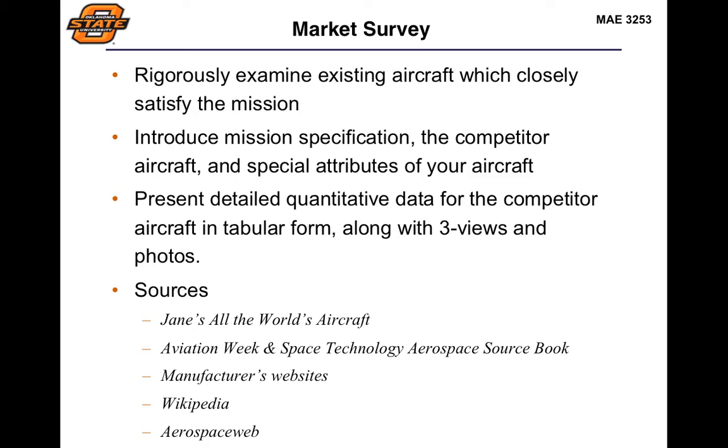Now, part of this benchmarking is looking at the market survey, right, where you go out and you look at existing aircraft which are going to closely satisfy the mission requirements that you have. So what you need to do is look at similar types of missions, because they don't have to be exact. Think about this from a payload capability, a physics standpoint, the type of environment it's going to be flying in, and then start to differentiate how your aircraft needs to be different based upon the overall requirements. And then you can use this benchmarking, right, to start to drive some of these comparisons.